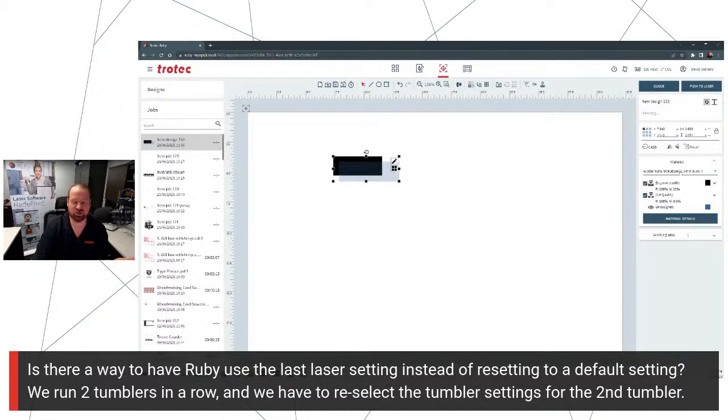You can adjust which color engraves first. You can also engrave multiple overlapping. So it'll engrave the settings for the black, and then it'll engrave the settings for the blue, even if it's overlapping. So for example, if I have a direct overlap and I want to engrave at high power with the color black, but then I want a cleanup pass with the color green, it'll engrave the exact file twice, but with two different power settings.